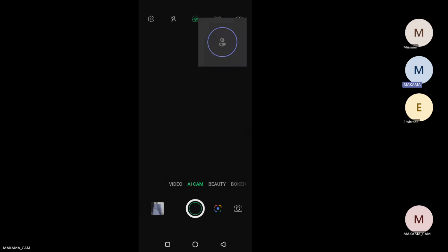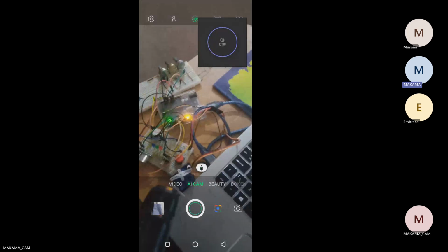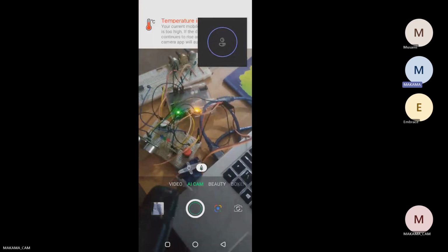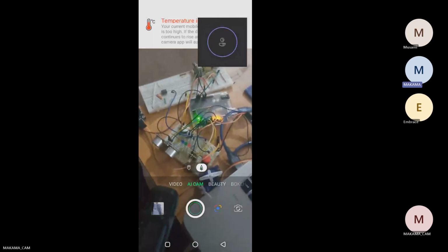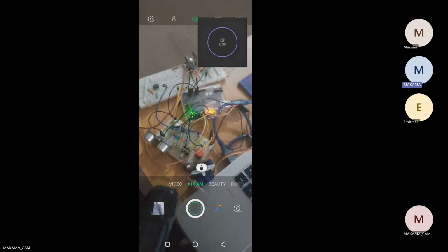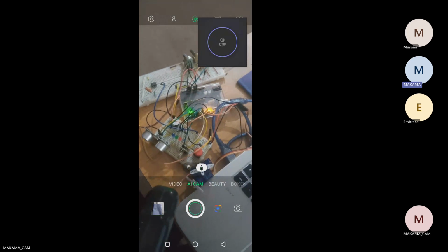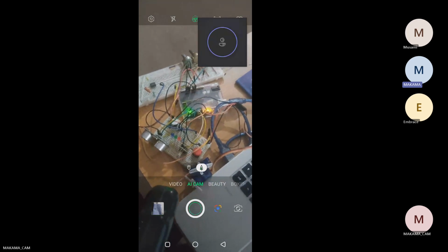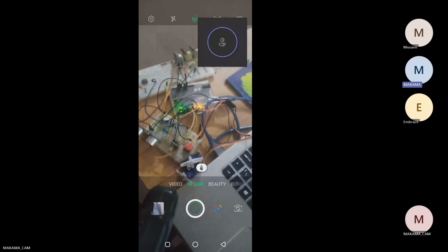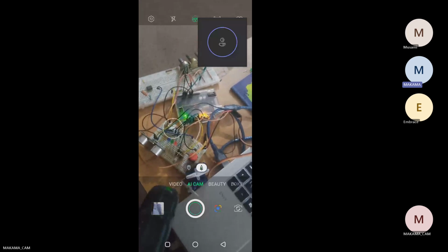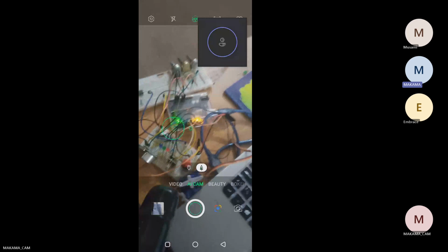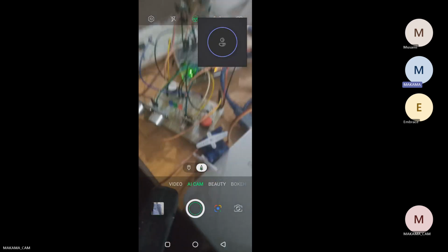So these are the major recommendations that I have for you in using external devices and motors that consume power. Sometimes when you use them, they affect the performance of your Arduino, because they consume a lot of power. Though the Arduino has been designed to be very protective, it can burn your Arduino because it is consuming power it cannot handle.